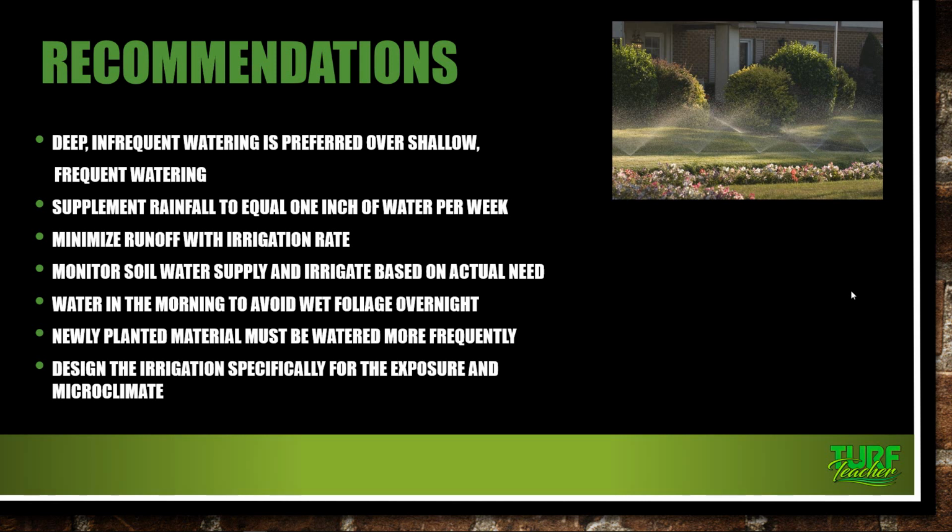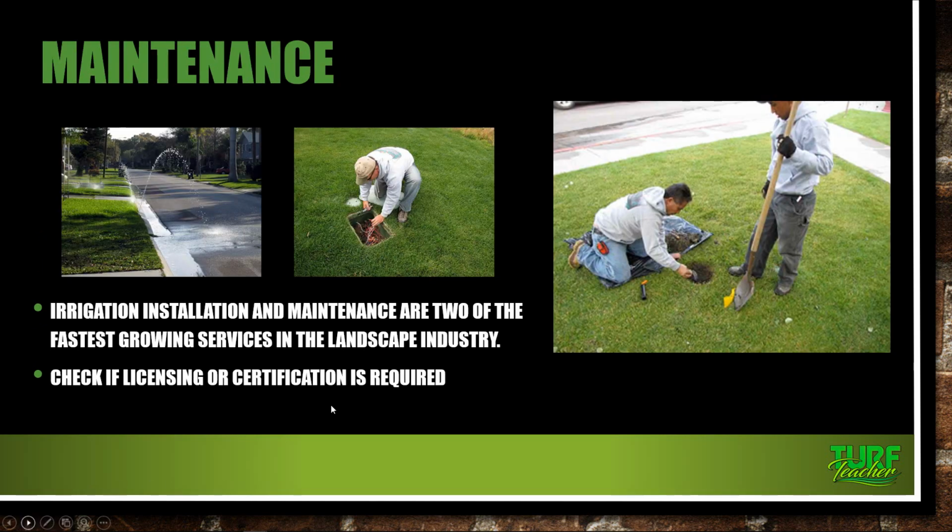All you're asking for is disease to set in and actually do more harm to the plant than help it. Newly planted material must be watered more frequently, and then design the irrigation system specifically for exposure and the microclimate that the plant material is in.